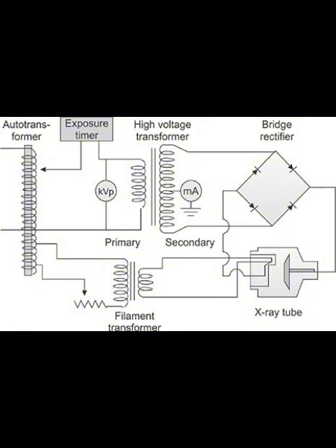And then there's a really specialized, incredibly useful performer. It's called the autotransformer. Autotransformer. Okay, how's that different? Well, unlike the regular step-up or step-down ones with their two separate coils, primary and secondary, the autotransformer is unique because it uses a single coil of wire. One coil does both jobs. Sort of. It has connections, or taps, at different points along that single winding. And by selecting different taps, you can vary the output voltage relative to the input voltage.